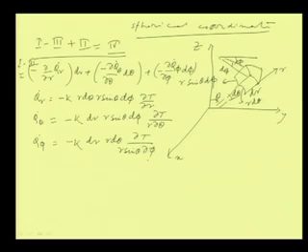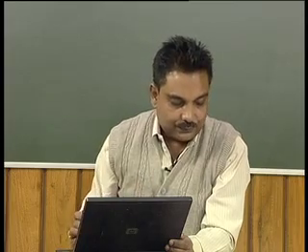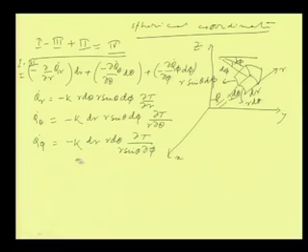Okay. Now, once you put these things together in the previous equation, then what is 2, the generation term? It is equal to q dot generation into dr, r dθ, into r sin θ dφ. So, this is the volume element into this, so it is the total energy generation.